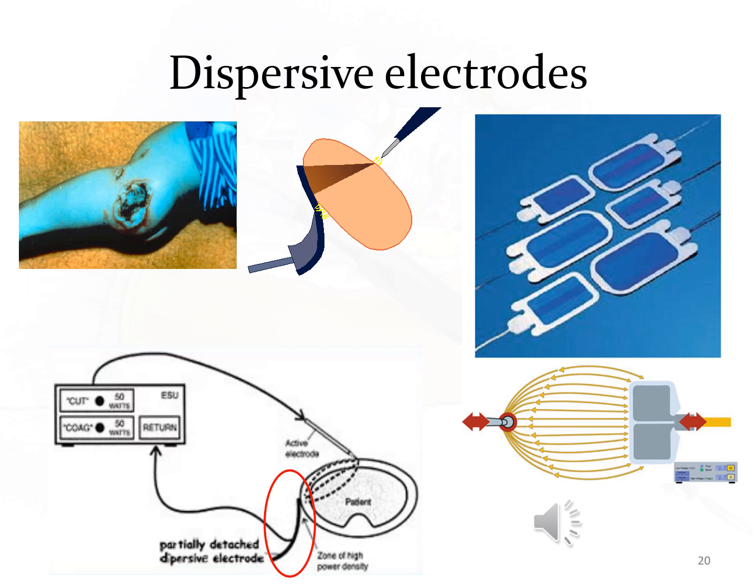Dispersive electrodes are almost always designed with an adhesive to facilitate continuing contact with the patient and prevention of a clinically significant local thermal effect. However, if there is partial detachment, the current density will increase and the dispersive electrode can become active and capable of creating thermal injury, often called a burn.